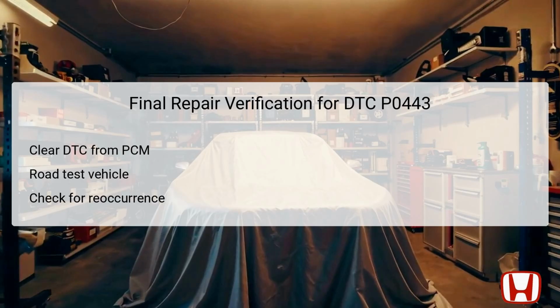During this test, monitor the vehicle's performance, especially noting any anomalies related to the EVAP system. After completing the road test, recheck for any DTCs using the HDS tool. This final verification step guarantees that the repairs were successful and that no further issues are present.